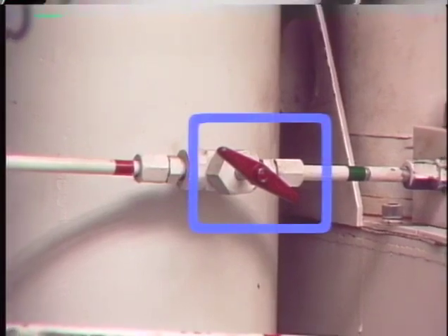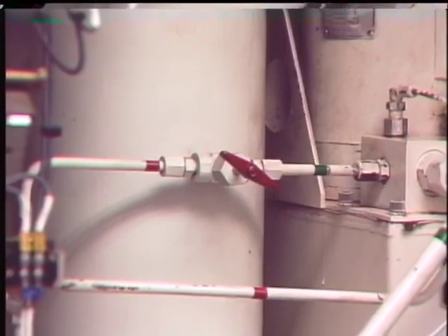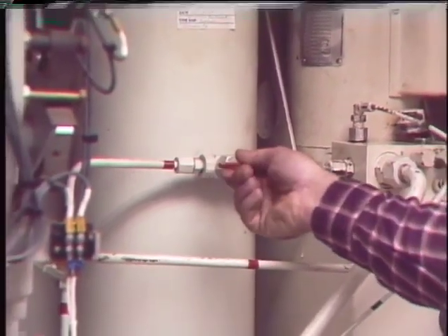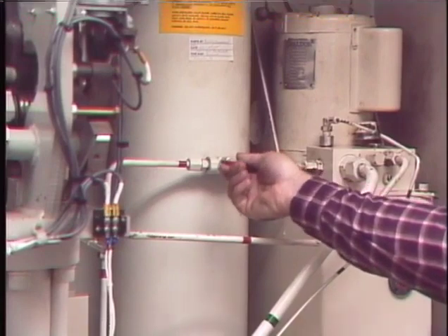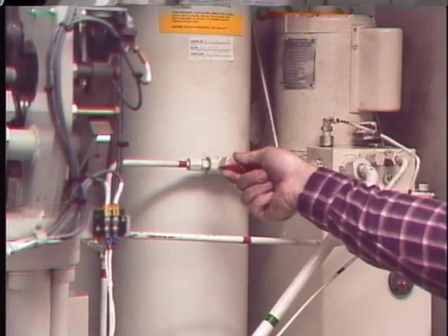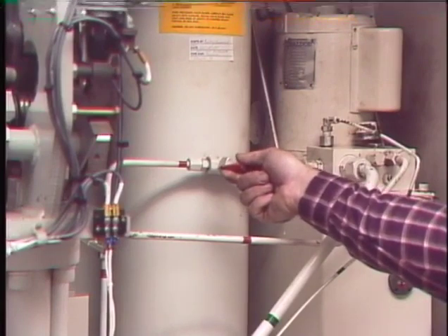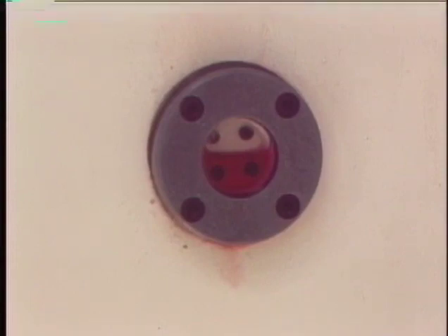Then a pressure bleed valve is partially opened to slowly bleed pressurized fluid into the low-pressure reservoir and reduce system pressure to zero. The valve is only opened part way, and it is closed from time to time to keep the fluid from foaming in the low-pressure reservoir. When system pressure is at zero, the bleed valve is closed and a fluid level check is made. With pressure at zero, fluid should be visible in a sight glass near the top of the reservoir. If fluid is not visible, fluid may need to be added to the system.